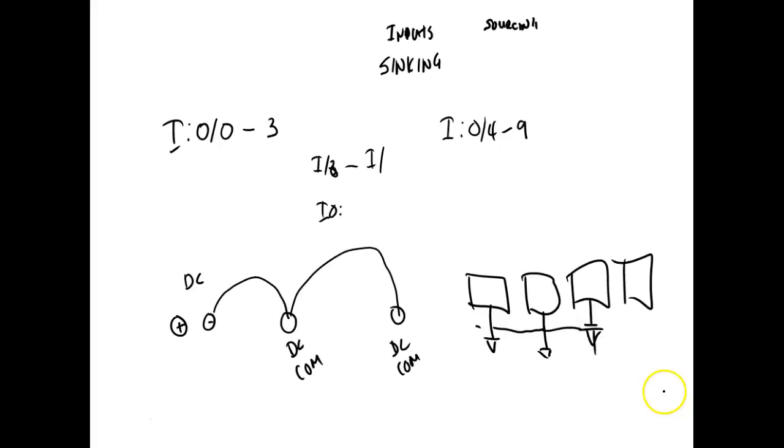So I've got these jumped together. In fact, that's not the way it actually goes. And we've got two commons. So what's it looking for? What's got to come in on this side right here? Power. Okay. So I'm going to come up here and hook up, let's say, a bunch of push buttons. Well, what's got to be common up here? Power. So I've got to hook up the plus there. And then I would run that plus over to here, right? You understand, to the next button.